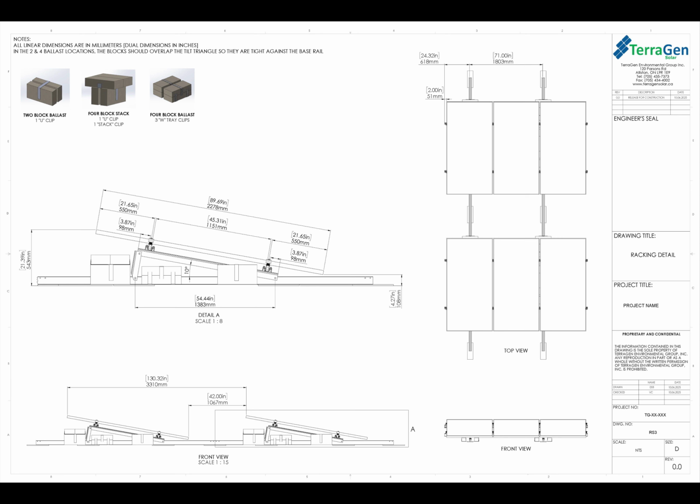Additionally, you can also install those cross adapters where those paint markers are, so then when top rails are getting installed, you already have those starting points with the paint marker or the cross adapters, so you know exactly where your top rails need to get installed.